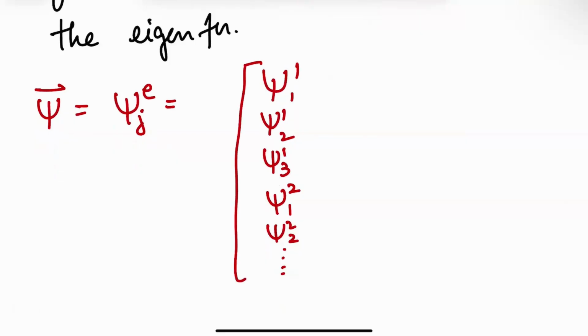So this big vector of unknown quantities, what's the dimensionality? So you have 3n cross 1. Right? That's the size of this vector. Because you have n mesh elements, and for each mesh element you have 3 nodes. Now, of course, many of the nodes are shared, so the final psi is actually not this, but the psi that we are dealing with so far is this. And several of the quantities in this vector are repeated because they are shared nodes. Right? But for now, let's just treat it as completely unknown. We're ignoring the part that the nodes are shared.